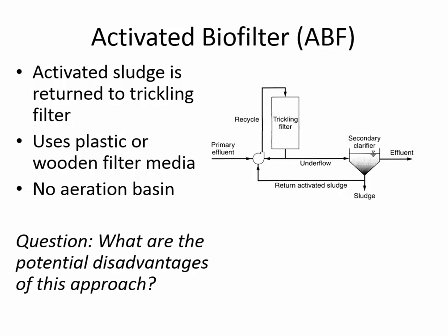So what are the potential disadvantages of this approach? It's that the sludge makes the possibility of clogging of the filter much higher than if you're not returning the sludge. So, not only are you returning the underflow, but you're also returning the activated sludge.